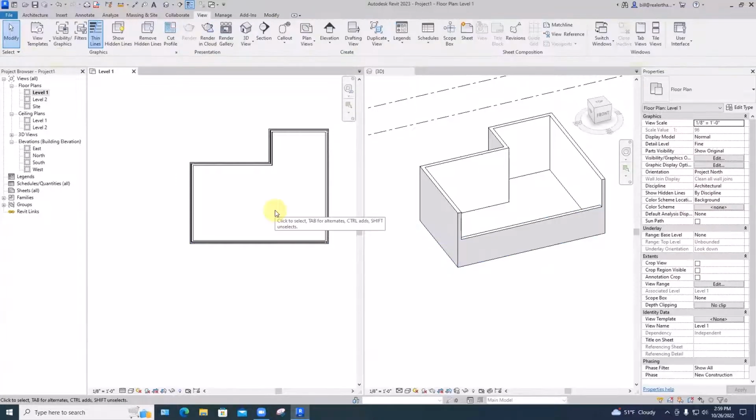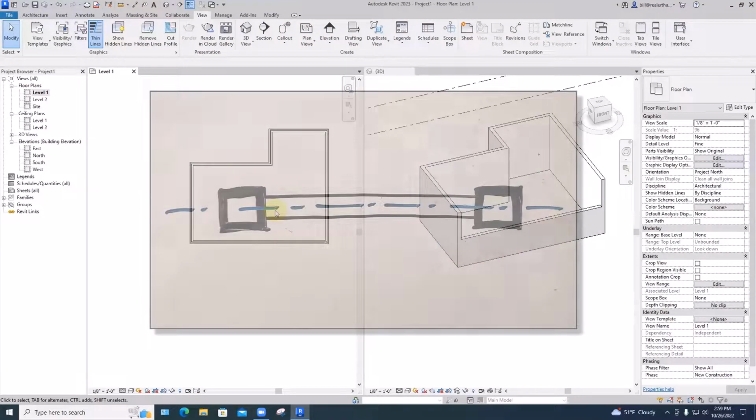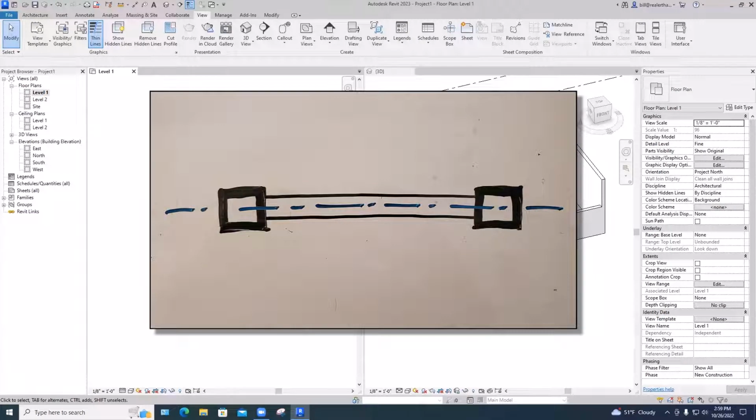When we're drawing each wall, we have three ways to draw it. Structural engineers almost always draw their walls using a center line, like sort of a point from here to here, because they're going to have a column here and a column here, and they want all those to line up on their centers. So if they're putting in concrete walls, concrete CMU walls or something like that, they will almost always be called center justified, drawn with the center line. And the cursor is here, and then the cursor is here, and then the wall goes out in either direction from there.